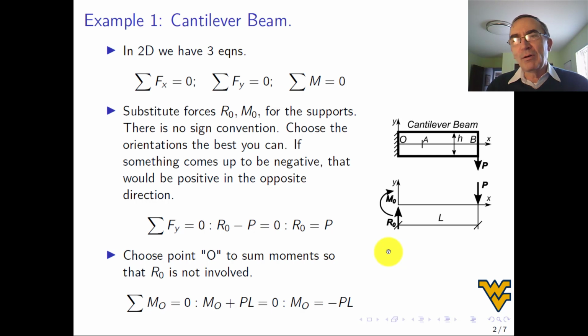So from now on, although in this particular lecture it's not important what direction you choose, it's better if we can start to get used to the convention for beams, which I will explain fully in another video or class later. So then we substitute the supports by reactions, forces, and moments. And then now we use the equations of equilibrium.